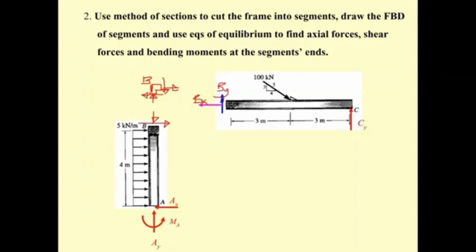You may do the detailed calculation by putting the column, but you also can skip this and transfer it directly in the condition that there is no force and no moment acting at that joint. If there is moment or force, we cannot transfer this directly.